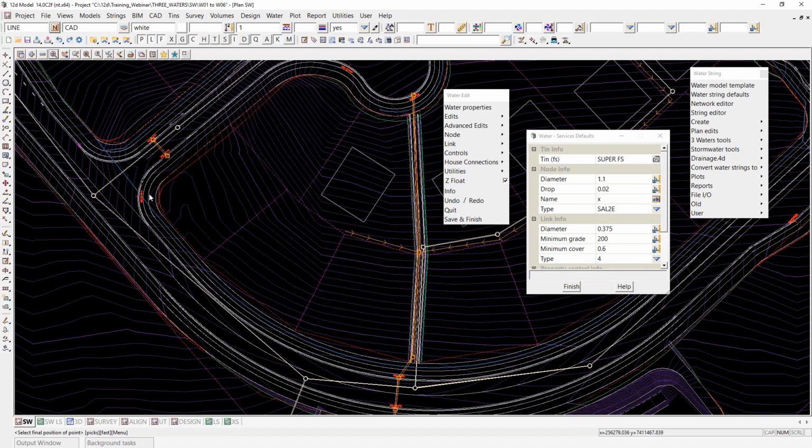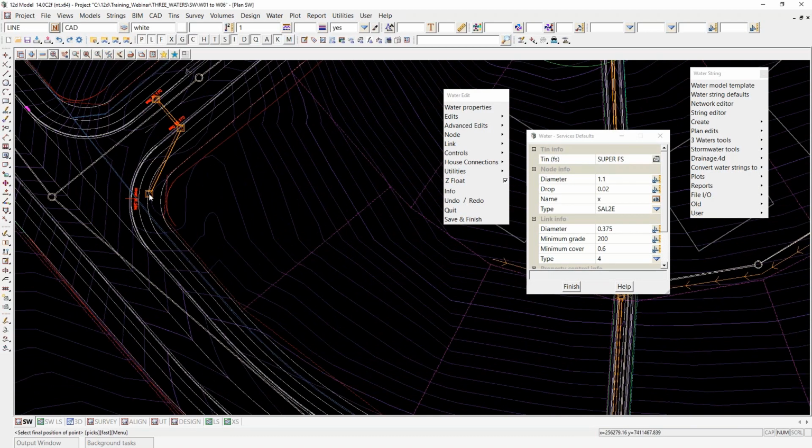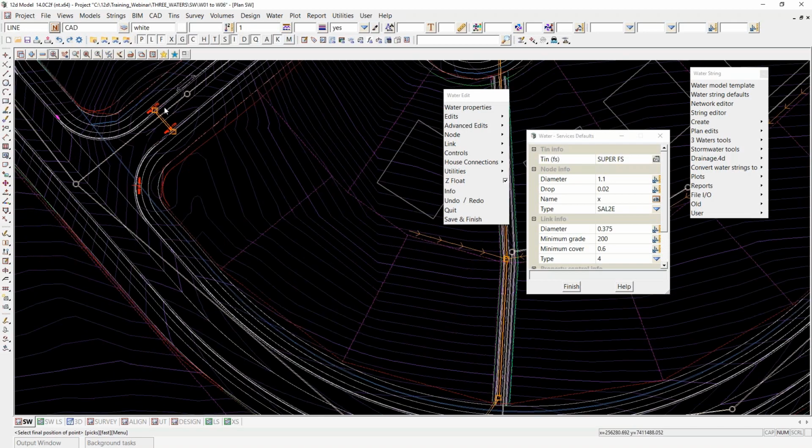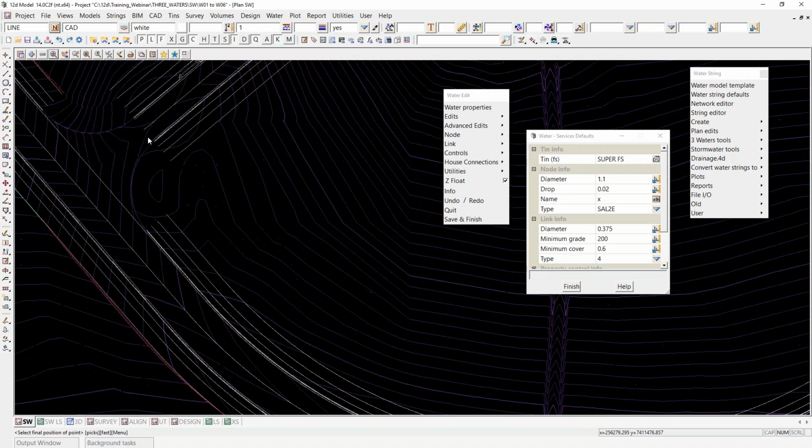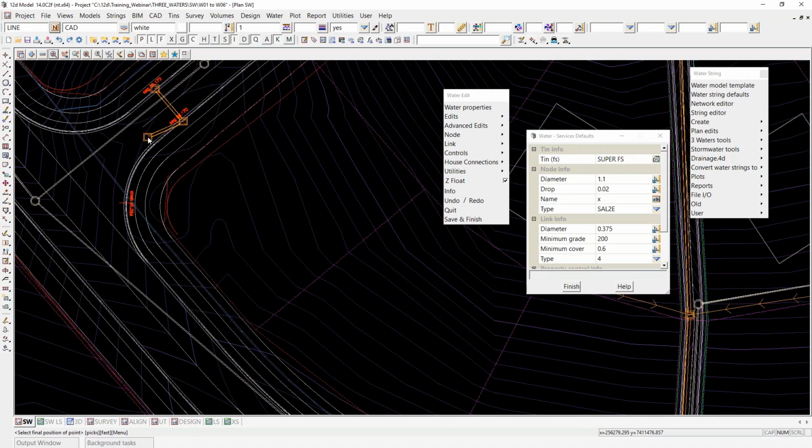Okay, so there's various rules that various councils will have here. Some places will say, well, you can't put manholes in the roadway, and some places say they'd rather you not put manholes in the verge or under footpaths or whatever. So today I'm just going to make a decision and say, well, it's preferable to place the manholes in the roadway. Now, again, there's lots of different ways you could achieve a design like this to get point A down to point B, if you like. And I'm just going to show you one possible way.